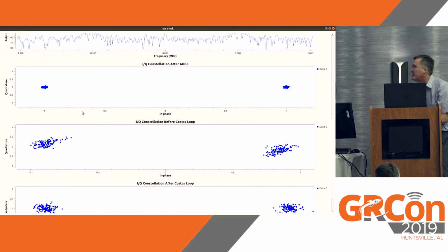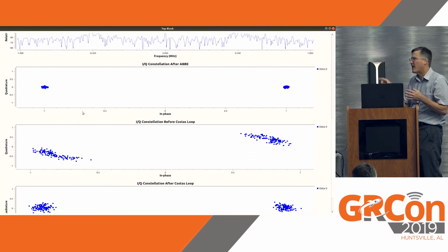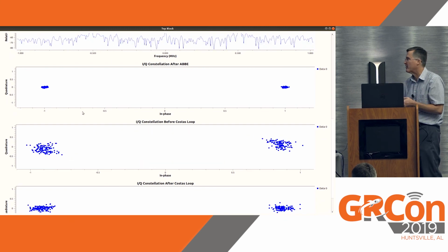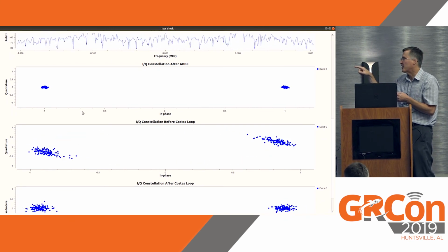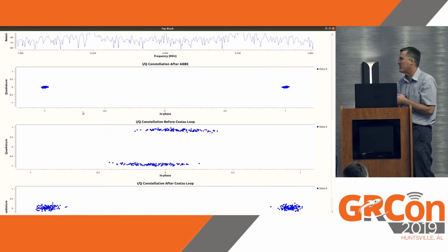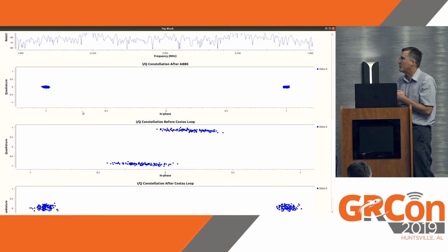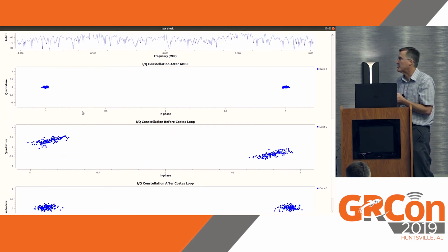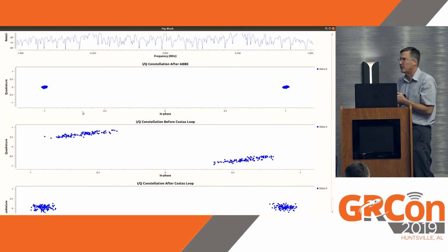Okay, I got it. Here's the rotation. You can see that one. On the vendor modem, it was kind of more constant and slower. This is a $90 signal generator. It probably doesn't have a great oscillator, but it still works. The IQ constellation on the bottom is right after the Costas loop, so it's pulled it out, gotten rid of the residual frequency offset. And then the one at the top, the one that says ABI, we call them adaptive baseband equalizers. You can see that the constellation has been tightened up. So this is basically what I was looking for.